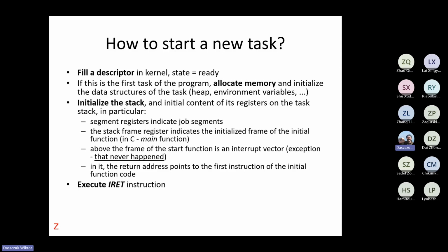If it is the next task, we must do some memory allocation, but limited only to the task stack, because we need as many stacks for threads as is the number of the threads. When we start a new thread, we must cut some memory from the program memory and allocate a stack for this thread.